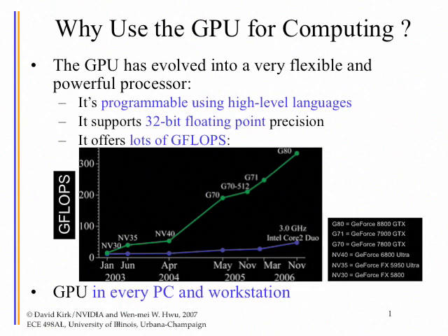And the reason why these chips are running too hot is because CPUs have been designed with the philosophy of very high clock frequency. And whenever you run the clock frequency at a very high level, you need to be able to drive the current very quickly, so that consumes power. And also, the actions happen very quickly, so you do the switching more quickly.